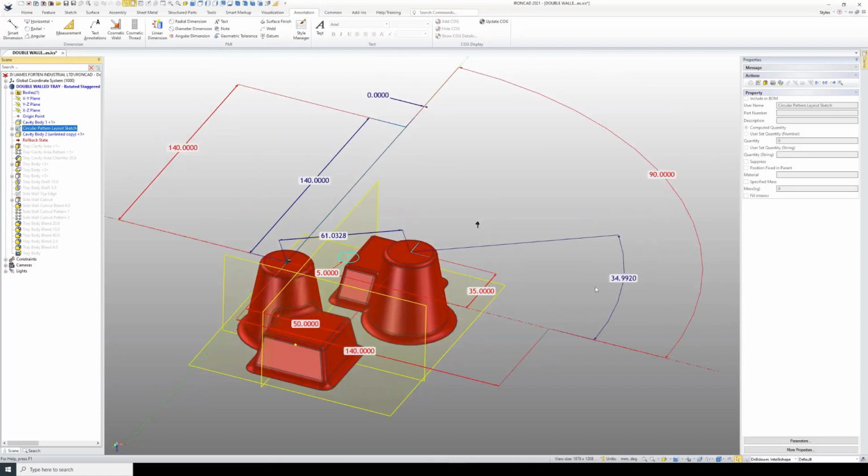And so I've got some options here within the sketch regarding how I position the second body. So for example, instead of driving it by using X and Y dimensions, I can unlock these dimensions. Again, I'm right clicking on them, and I can use polar dimensions instead.